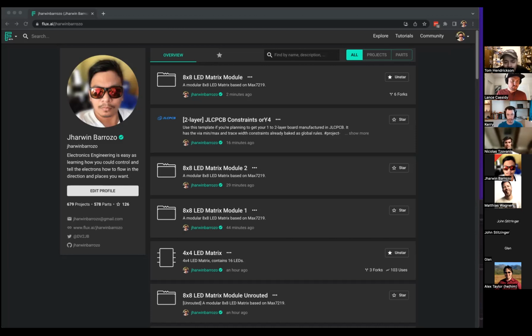Oh, great. Actually, the project that I've been using as my export test, the one that's coming out on top of each other, is not made up of sublayouts at all. I guess the problem was the offsets, right? The texts are not at their proper location. It looks like the text is all coming out on top of each other in the center of the board. It's not picking up. Can we take a look?